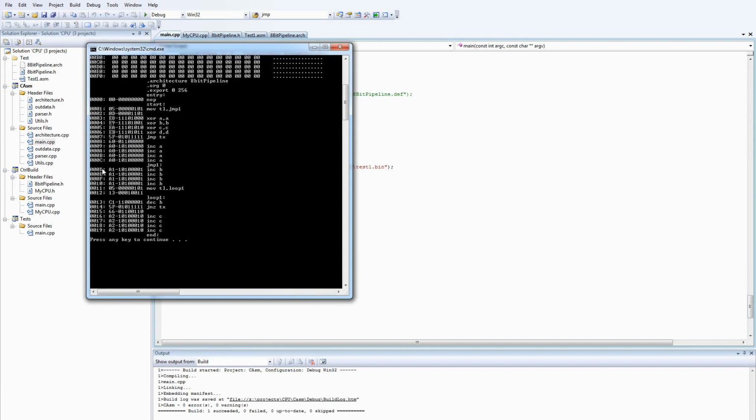There you go. So this is outputting the opcodes of our program, but it's giving the bytes in both hex and binary and the address that we're writing into the ROM. So jump TX is coming out as 5F60. So that's the actual jump there, and that's our pre-branch instruction. So we're kind of faking an extra layer of functionality. It does mean that our branch instructions have now become 3 cycles instead of 1. But we don't have to add those NOPs around them either. So our peak performance is lower.